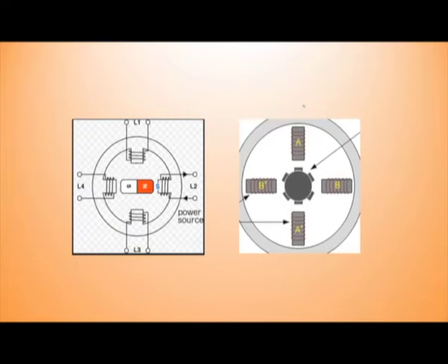Suppose we have 4 coils. I will name them A, B, C, D. Only some of the signals are on, suppose here both are 1, and these two are 0. Here the coils are connected such that A and B are commonly connected, that is the unipolar. These two, C and D, are commonly connected. If any one of the coils is energized, then automatically it starts to rotate.